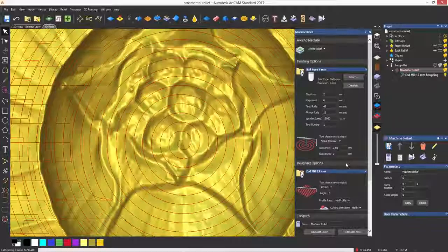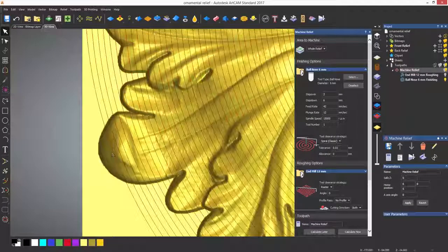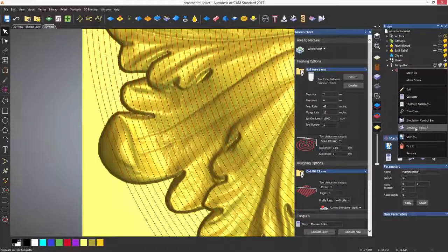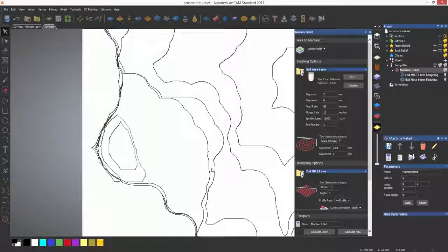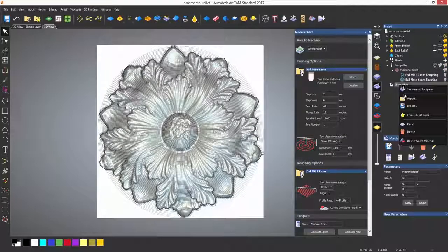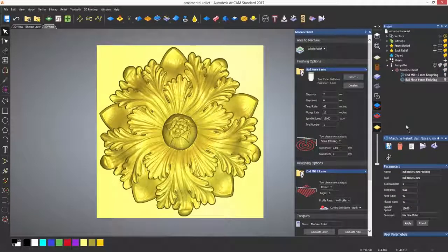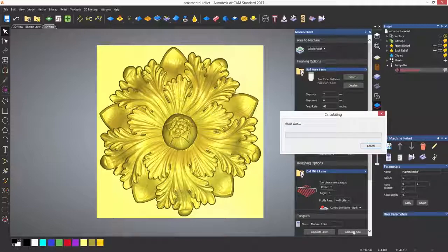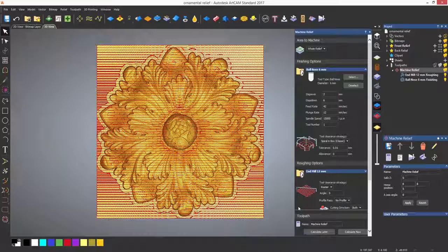You may notice that the spiral toolpath has not machined the whole of the relief. This is because it spirals outwards, and as soon as it touches the edge of the model, it finishes. If I choose the spiral in a box strategy, it will then machine those areas, do it within a box, which is basically the whole of the relief.